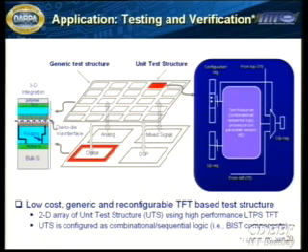The other interesting thing to note is that the multi-finger design turns out to be a little bit different from having a wider transistor. The reason is that if I have a wider transistor, I'm going to be dealing with a lot more grain boundaries. And if I use a multi-finger structure, I'm going to get a better design because of the cancellation nature of it. So then what we did is we looked at digital, DSP, mixed signal and all kinds of different circuits in this domain, and then came up with a generic test structure, which is basically going to test the underlying CMOS circuits.